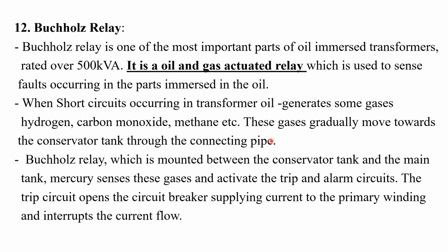The last important requirement, that is the Buchholz relay. It is the most important part of an oil-immersed transformer rated over 500 kilovolt ampere. It is a gas actuated relay. It can be used to detect the fault that occurs in the transformer main tank. Okay.